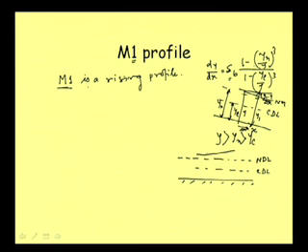Now, as it is a rising profile, this profile, if we see on the upstream side, will gradually fall, and to what extent will it come? It will be coming to the NDL line, that is at the extreme upstream, the starting of the gradually varied flow profile.